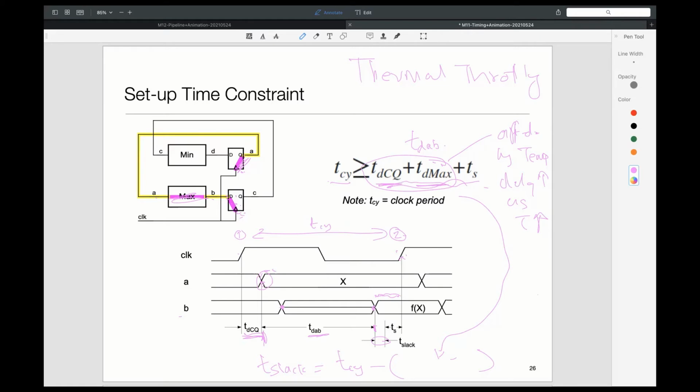And actually, there is an interesting feedback loop here, because the power your system consumes depends upon clock frequency. If you run it faster, it dissipates more heat. So you can have a situation of thermal runaway. You increase the clock speed, and as a result, more heat is produced, which causes the gate delays to go up. If you don't respond to it, the delays keep going up.